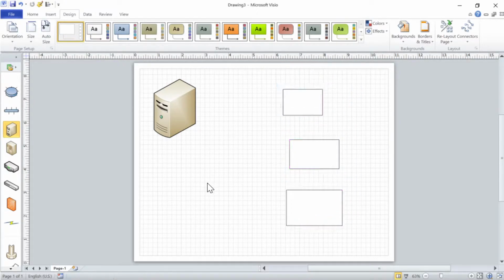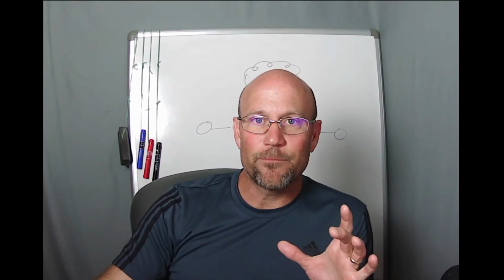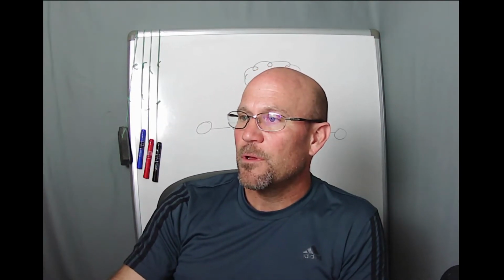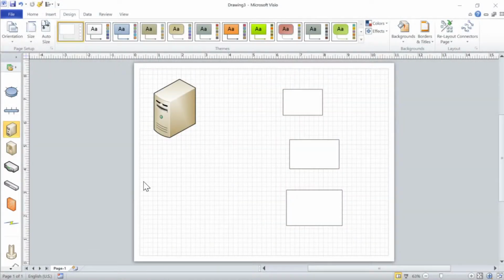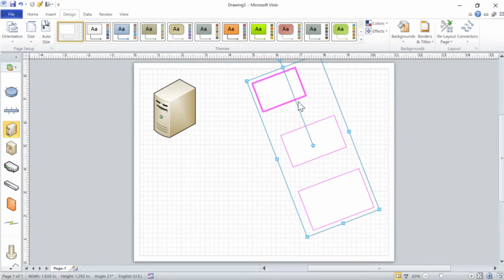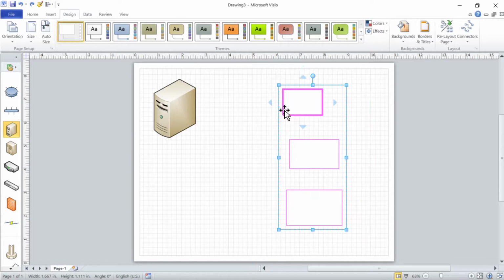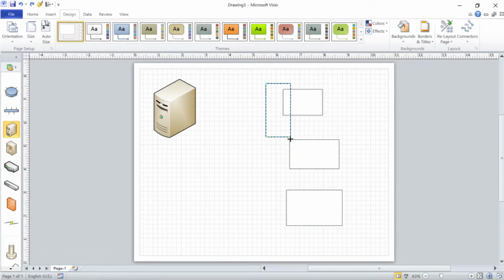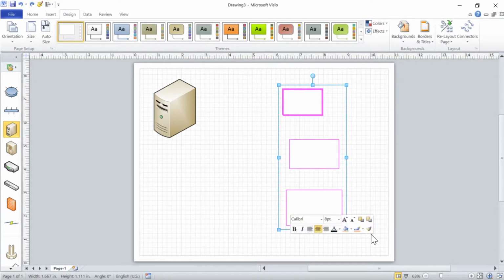So you can proportionally size all of them together when they're highlighted. The only reason you were able to do that is because you had highlighted all of them together with your left mouse key, dragging across them. And so you're able to, on the fly, treat them as one object. Now, if you want them to remain as one object, this is what I was talking about with the Control G keyboard hotkey.